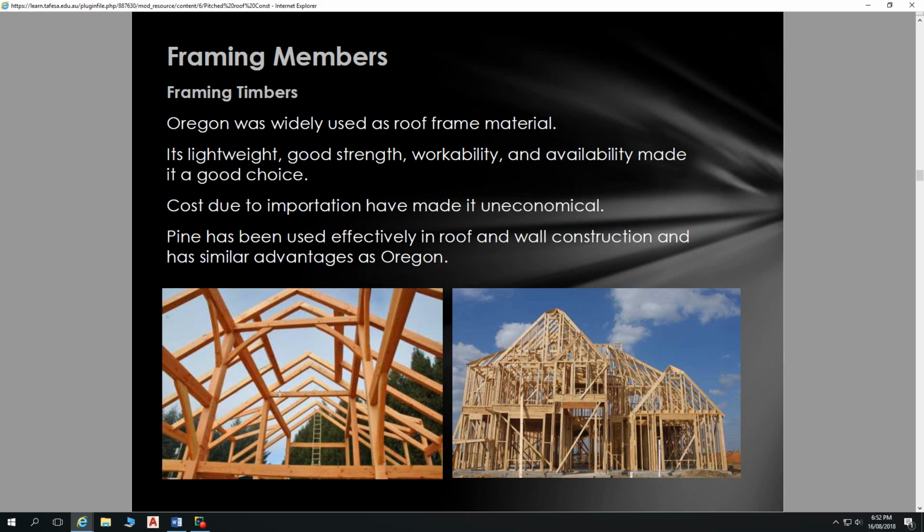It's also very nice to work with insofar as it's super light, but it has that strength. Like pine, you whack it with a hammer and you get a dent very easily. Oregon will certainly still dent, but it maintains its structure much better, which means fixings hold better in Oregon.